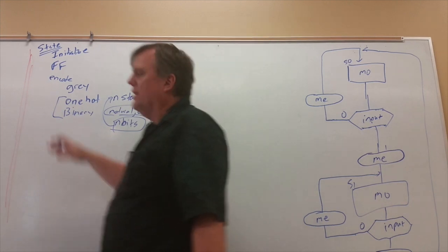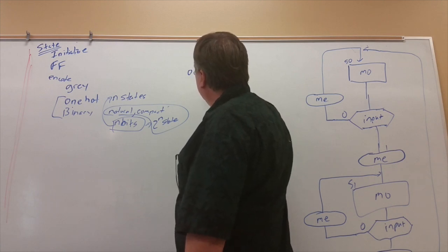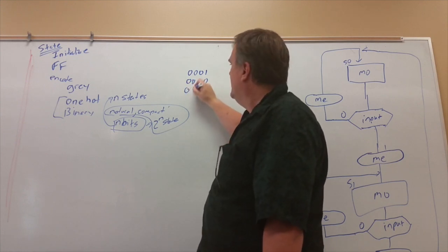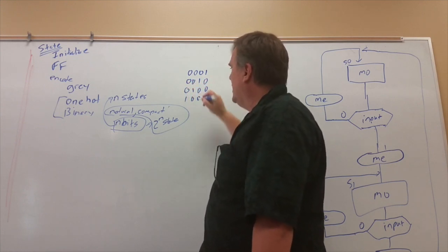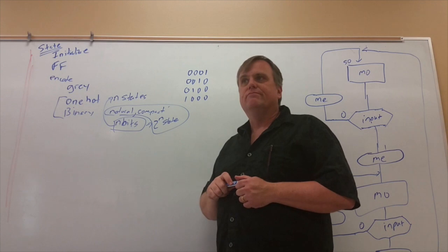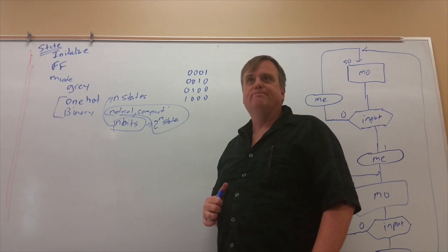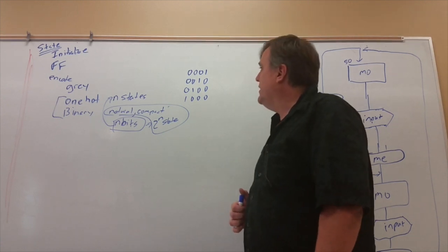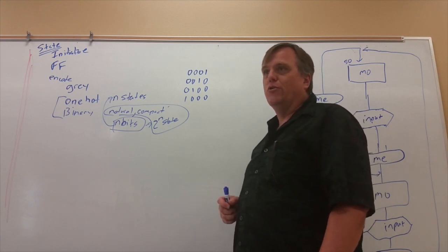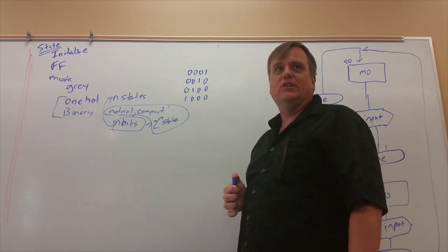The way one hot works, you know binary is your normal counting thing. The way one hot works is the first state, 0, 0, 0, let's say just it's 4, that's state 1, state 2, state 3, state 4, that's all you get. Right? Those are the only codes you use. Now, the reason why this one is nice, you can actually even see why it's called one hot. Right? Because 0 usually means ground, 1 means power. So only 1 bit is hot at any given time.